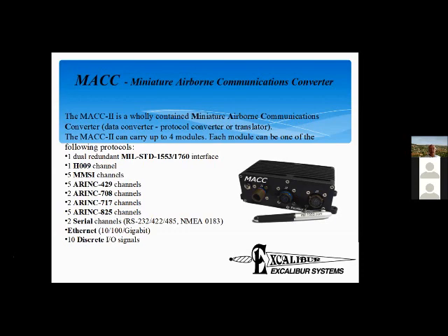What the MAC does is it takes this inertial navigation system, let's say it speaks Ethernet. It then gets the Ethernet message from the INS. It's smart enough to take apart the message and say, okay, what's in this message? It's got altitude and longitude and latitude and whatever else it's got. And then it acts as an RT, sending the same data under the appropriate subaddresses and the appropriate type of data.